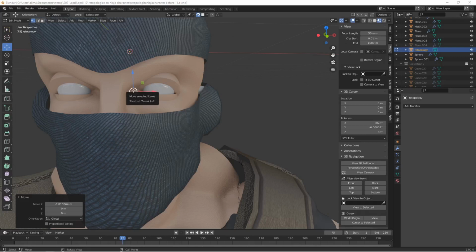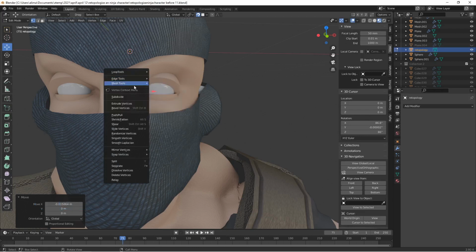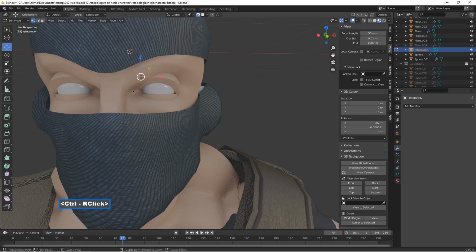Okay, so with this vertex selected, I'm holding control. Because I'm holding control, when I right click, I'm going to extrude a vertex out. So I'm holding control, I'm going to right click. Holding control again, right click. There we go. So there's 1, 2, 3. Those are the 3 vertices I talked about above the eye. Here's the 1 to the corner of the eye. Then 1, 2, 3. Those are the 3 I said beneath the eye. I'm letting go of control, holding shift. Selecting here, letting go of shift, pressing F. So now we have this loop going around the eyes.